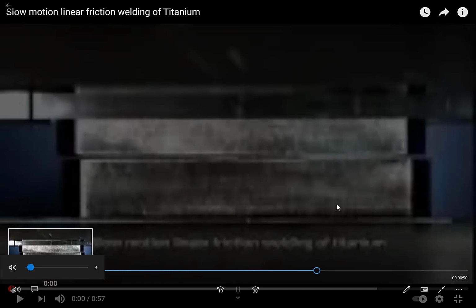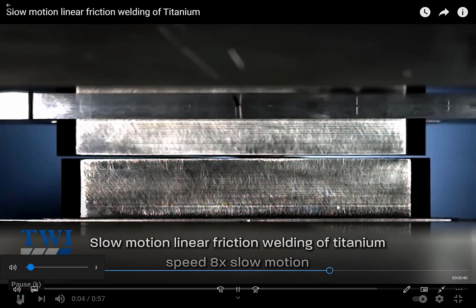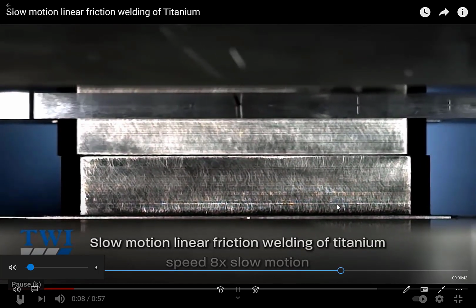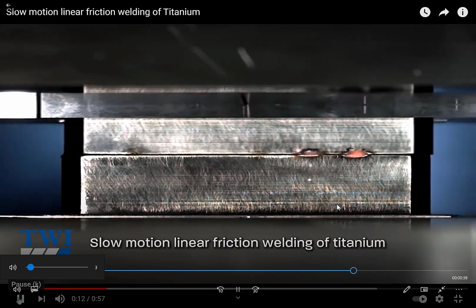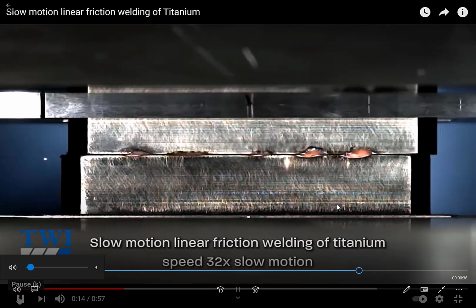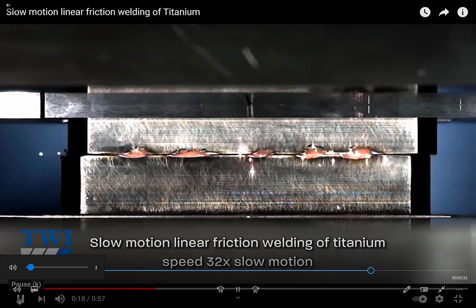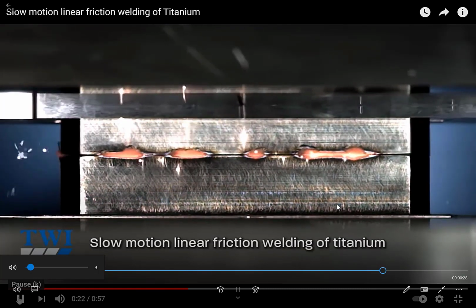Okay, this one is the linear friction, where reciprocating movement is given to one of the workpieces. So at the interface, through the frictional heating, heat is generated, and you will notice a localized rise in temperature at the faying surfaces, and that will lead to thermal softening.